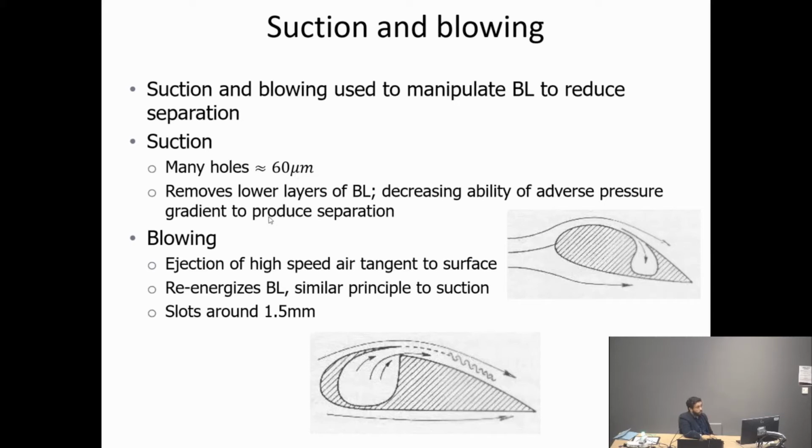They're quite small. What they do is remove the lower region of the boundary layer and keep the other part, which has more kinetic energy, and therefore the boundary layer will not separate as easily. So this is in a way similar to leading edge device effects.